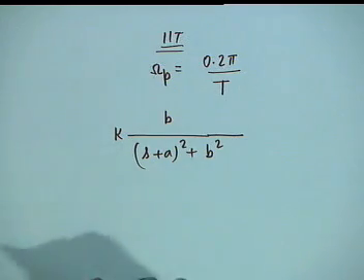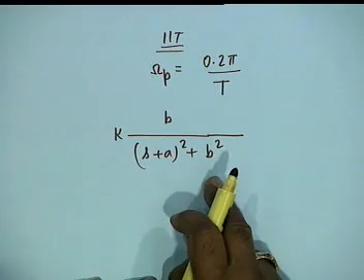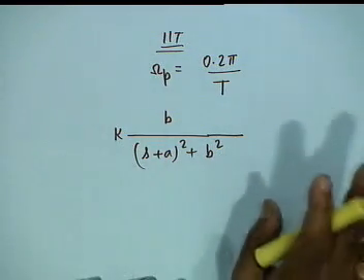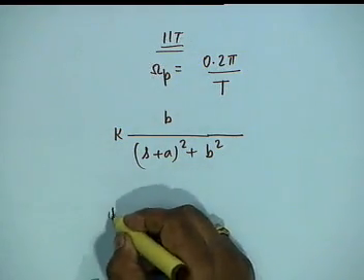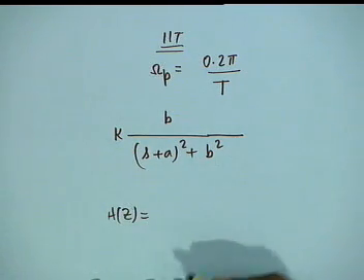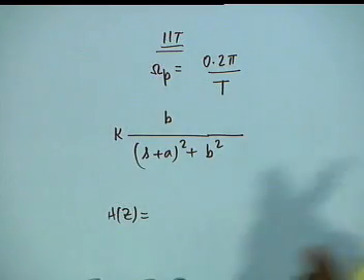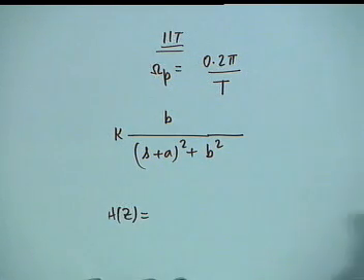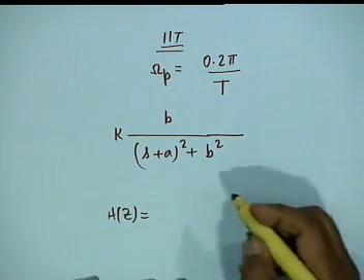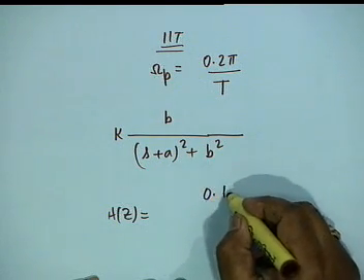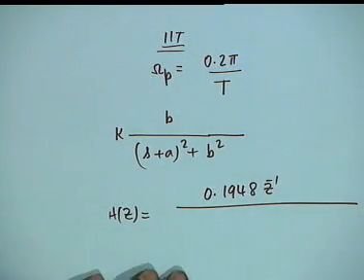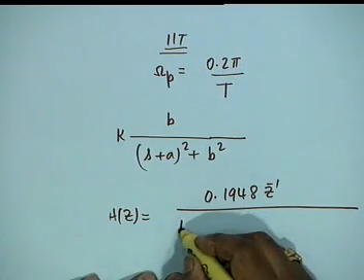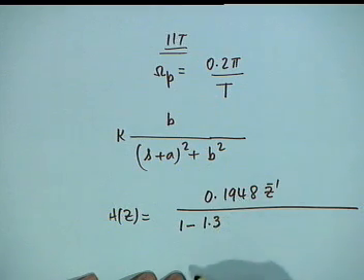This is impulse invariant transformation. So once you have obtained this, nothing else has to be done. You appeal to that formula and write the transfer function H of z as the constant k multiplied by e to the minus a t sin b t z inverse divided by the quadratic denominator. The final result is 0.1948 z inverse.